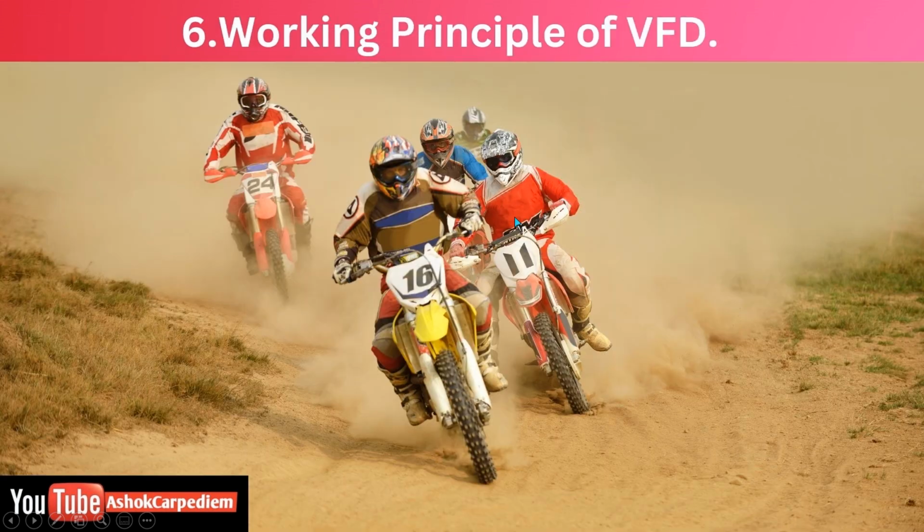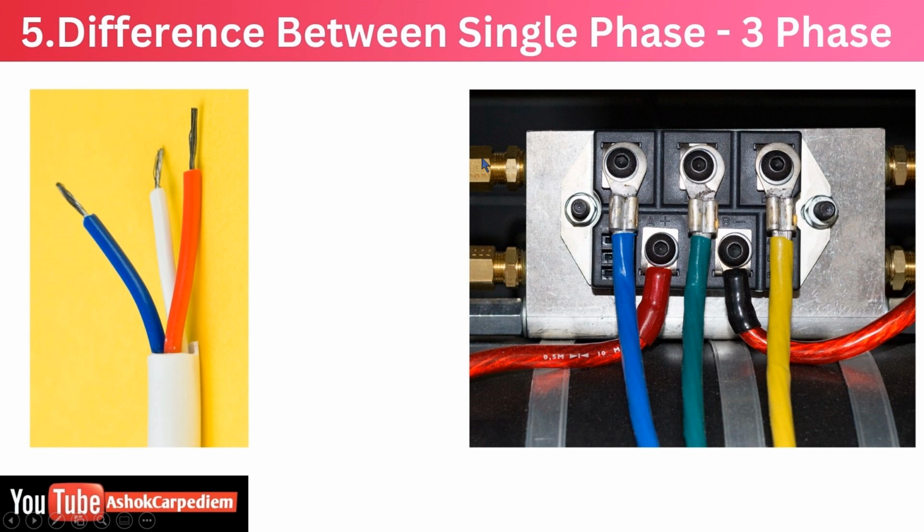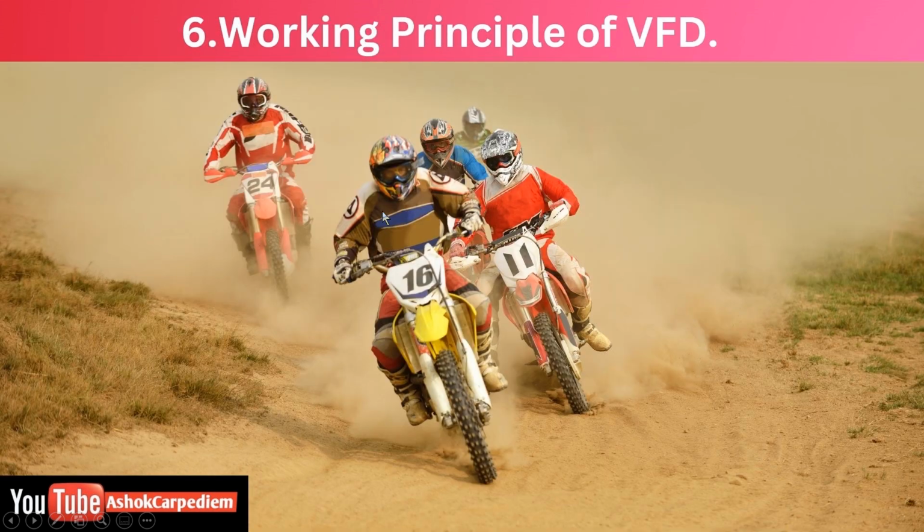I think I have missed my slides. No need to worry. In single phase we are using only two wires, one is the neutral and one is the phase, and another one is the earth. But here it is not like that, there will be no ground here. All wires have the same power, 230 volt, 230 volt, 230 volt. Power is coming in all three wires. That is the difference between single phase and three phase. Here it will be 230 volt and the total is 415 volt. That is the main difference. And next, the working principles of VFD.